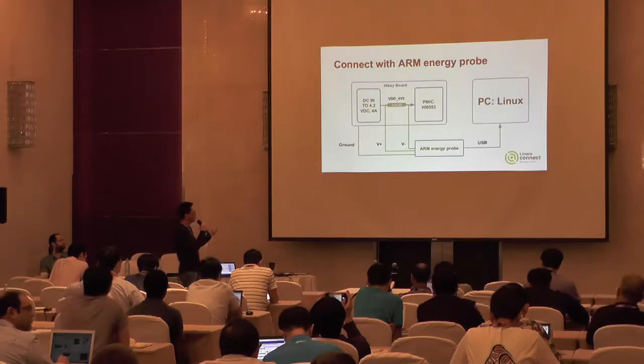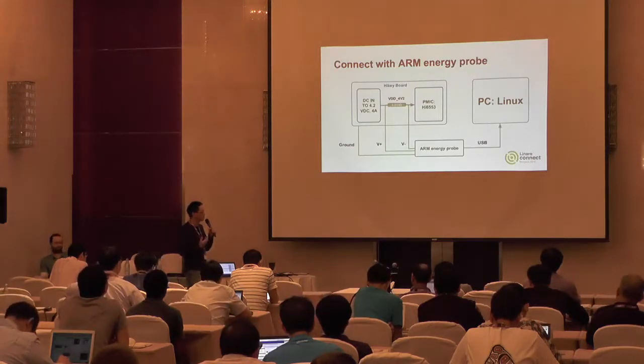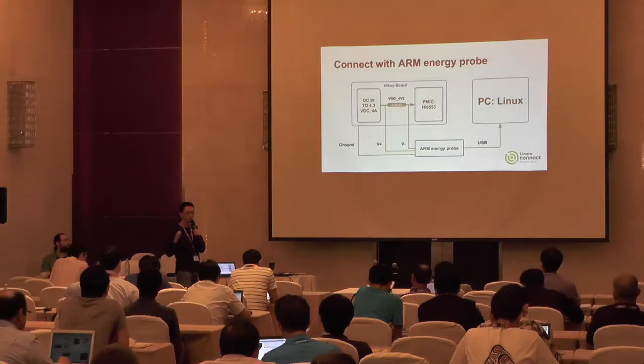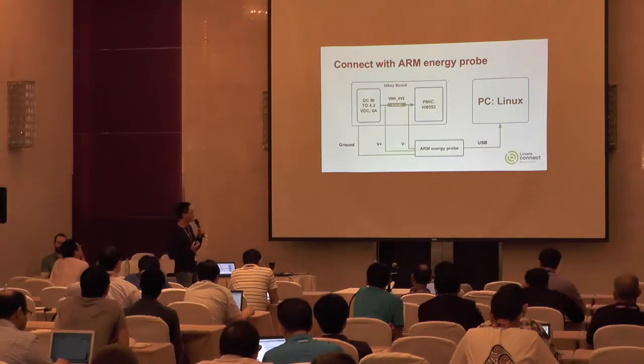Also, with the ARM Energy Probe, we can use some Linux program to capture the power data on the PC side. For example, ARM has developed the LISA framework, so you can use the LISA framework to capture the power data and also run the test case at one time. This is why we select the ARM Energy Probe here.